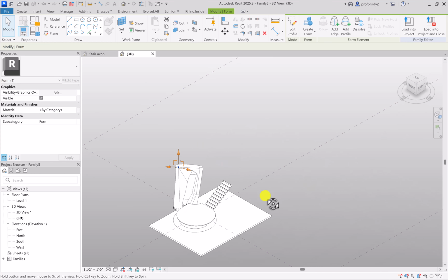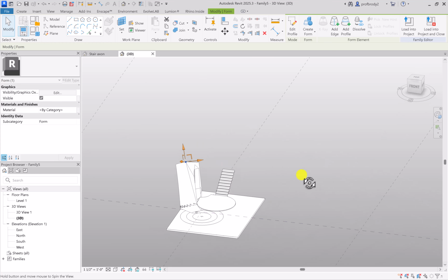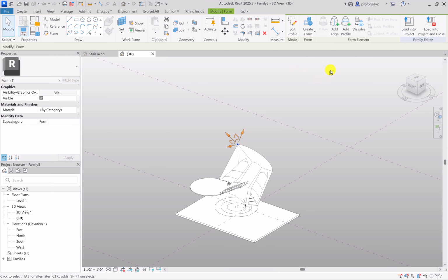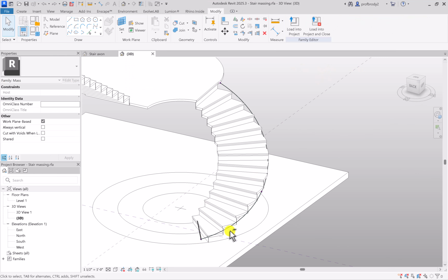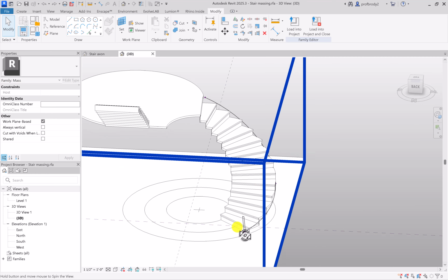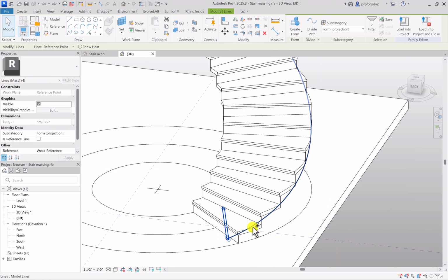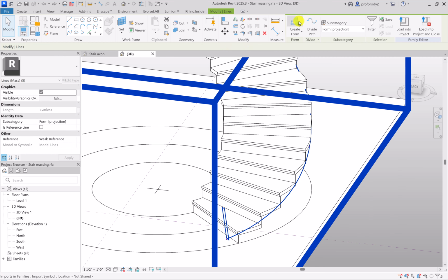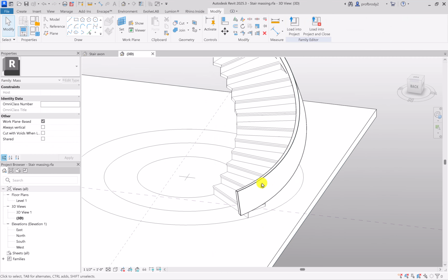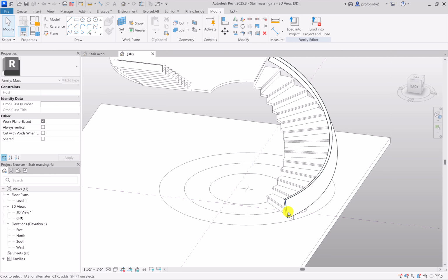Now, what if you wanted to just create a series of organic linguini type of shapes? Well, the linguini form is actually pretty straightforward. You just create a single shape at the end of the curve that we drew, the 3D spline. Choose Create Form, and there you go. You got yourself a form. And that form can be copied.